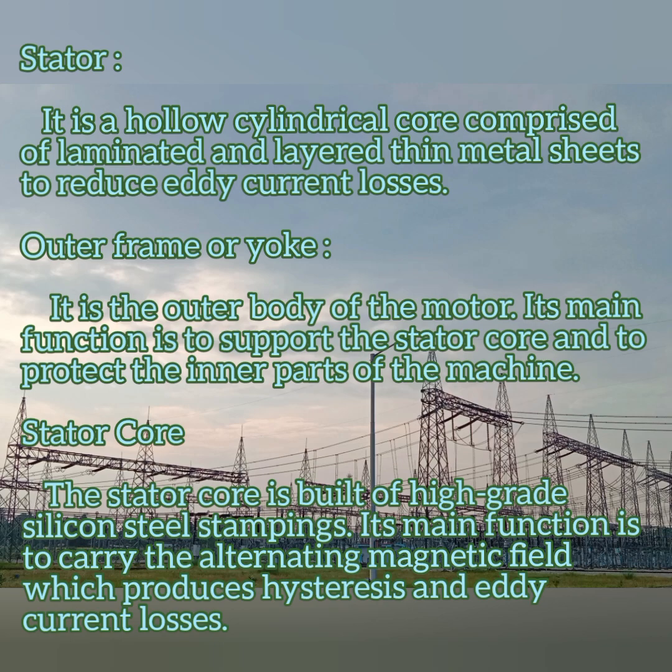Then the outer frame or yoke. It is the outer body of the motor. It functions mainly to support the stator core and to protect the inner parts of the machine. Then the stator core. The stator core is built of high grade silicon steel stampings. Its main function is to carry the alternating magnetic field, which produces hysteresis and eddy current losses in it.